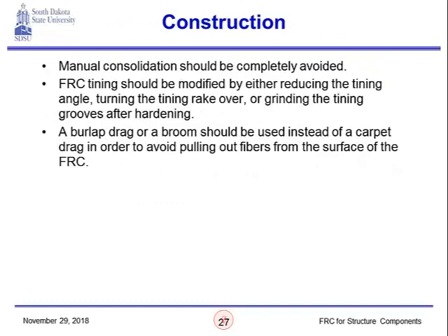Now, the recommendations for the construction: manual consolidation should be completely avoided. As I said, it's very difficult to work with FRC and to make sure it flows into the forms, and to make sure the fibers are uniformly distributed. It's better to have some kind of vibration when it comes to casting FRC.